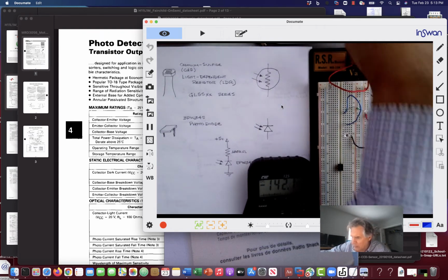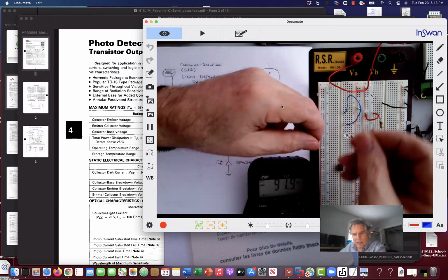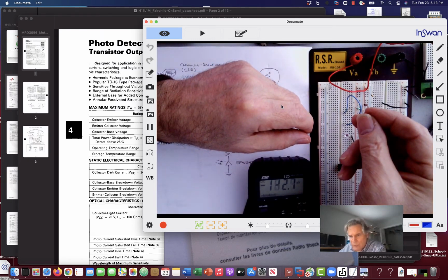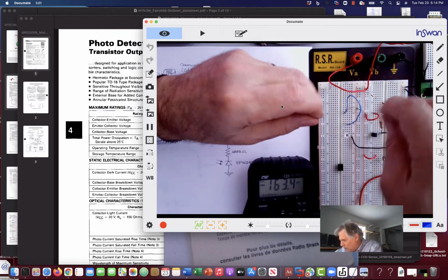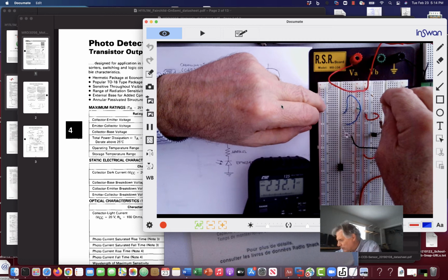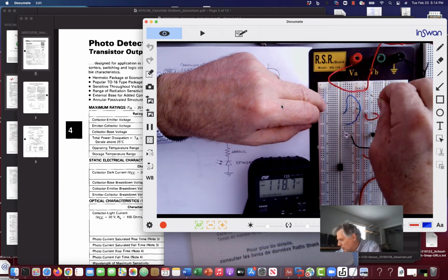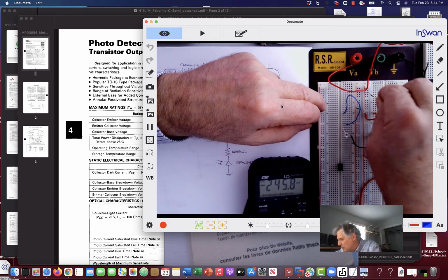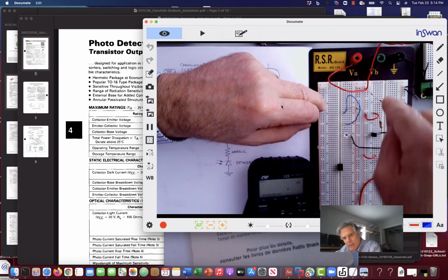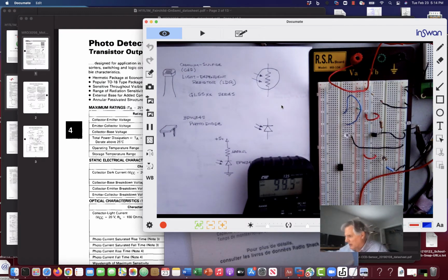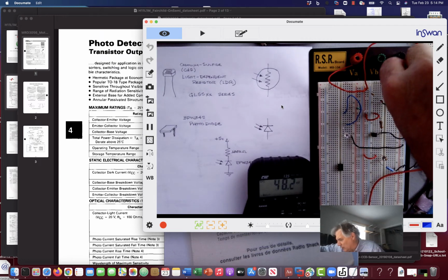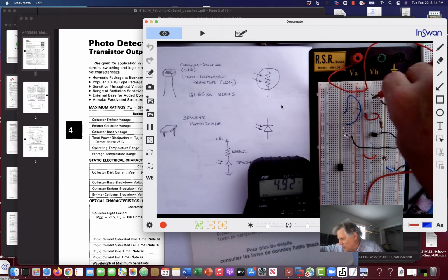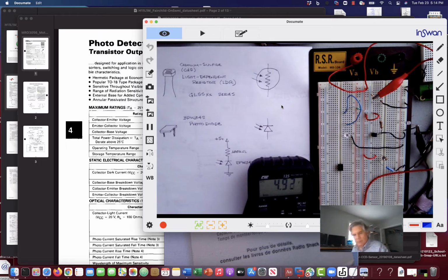I'm going to put in this diode, whose cathode is represented by that black bar, in this location here. Now that's a reverse bias diode. I'm going to put our voltmeter on there, and let's just see if a silicon diode will conduct any differently.